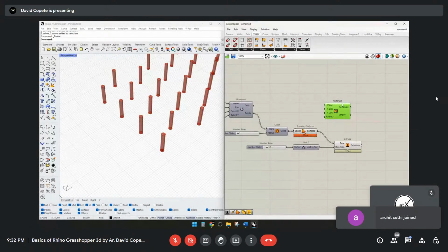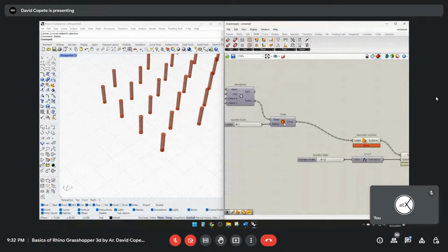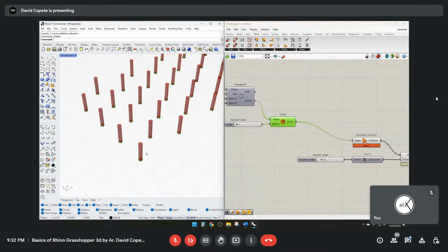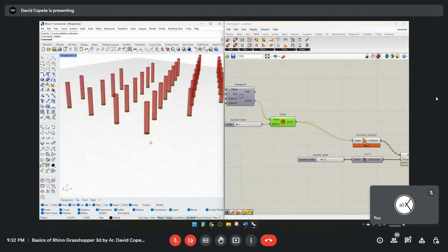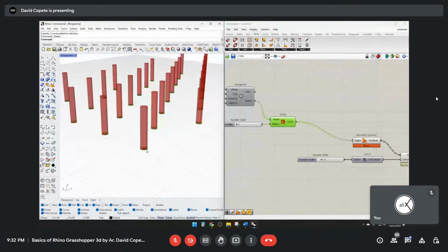Here's the thing. We'll get into that, but I think with the circle is going to be better. Let me show you what I mean. So we have these circles here. Well, let's say we want to create a footing below that. Well, we can use caissons, and the way to do that is we're going to offset this to the outside and then extrude it down as the foundation.